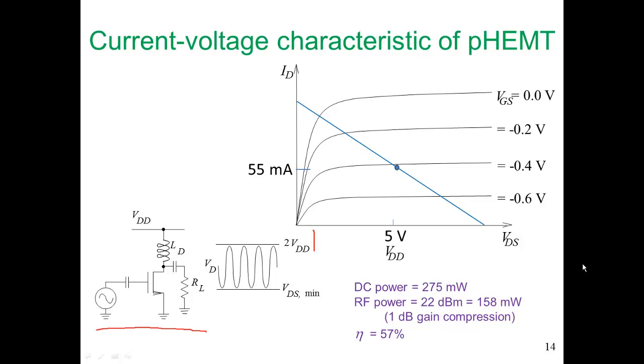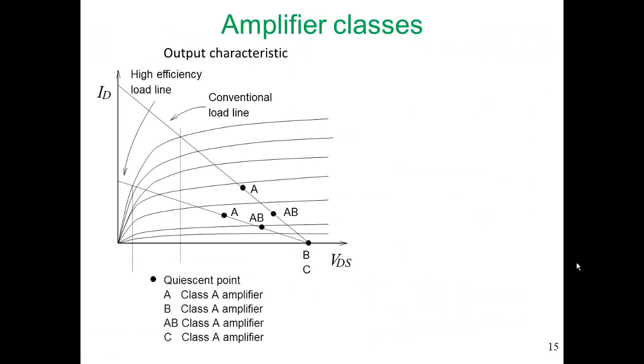But all this information, the efficiency coming out around about 57%, the fairly high level of DC bias current, and of course the manufacturer's current voltage characteristic, is telling us that the manufacturer really thinks this should be used as a Class A amplifier. They would have separate amplifiers if they thought this would be useful as a Class AB or B amplifier.